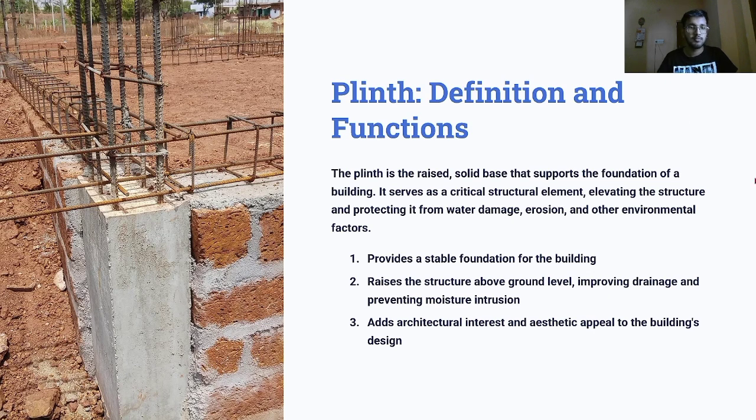Next, we have a plinth. As you can see in the photo, that's how a plinth looks. A plinth is a raised solid base that supports the foundation of a building. It serves as a critical structural element, elevating the structure and protecting it from water damage, erosion, and other environmental factors. As you can see, it is raised from the normal ground level so that there might not be any water passing through it and damaging the internal structure.